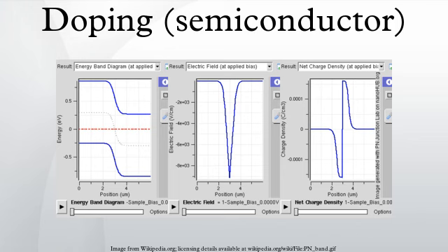Carrier concentration: the quantity of dopant introduced to an intrinsic semiconductor determines its concentration and indirectly affects many of its electrical properties. The most important factor that doping directly affects is the material's carrier concentration. In an intrinsic semiconductor under thermal equilibrium, the concentration of electrons and holes is equivalent. That is, if we have a non-intrinsic semiconductor in thermal equilibrium, the relation becomes n0·p0 = ni², where n0 is the concentration of conducting electrons, p0 is the electron-hole concentration, and ni is the material's intrinsic carrier concentration.